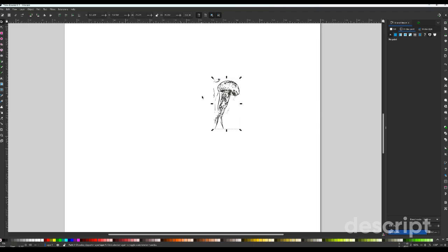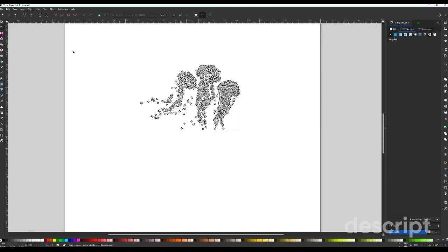I don't want that in my image, so I will show you how to delete the nodes, which are basically little areas that tell Inkscape where to draw. So deleting them basically gets rid of the drawings. Okay, so to delete a node, over here is how to edit the nodes.